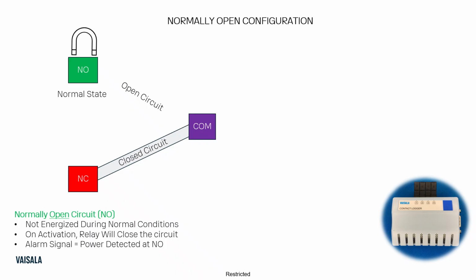So in a normally open configuration, these are the same three terminals that were in that graphic from before, where the COM has a switch that goes between the normally closed and normally open contact inside the relay. And under normal conditions with no magnetic pull towards the normally open contact, the circuit is closed between the normally closed contact and the common.